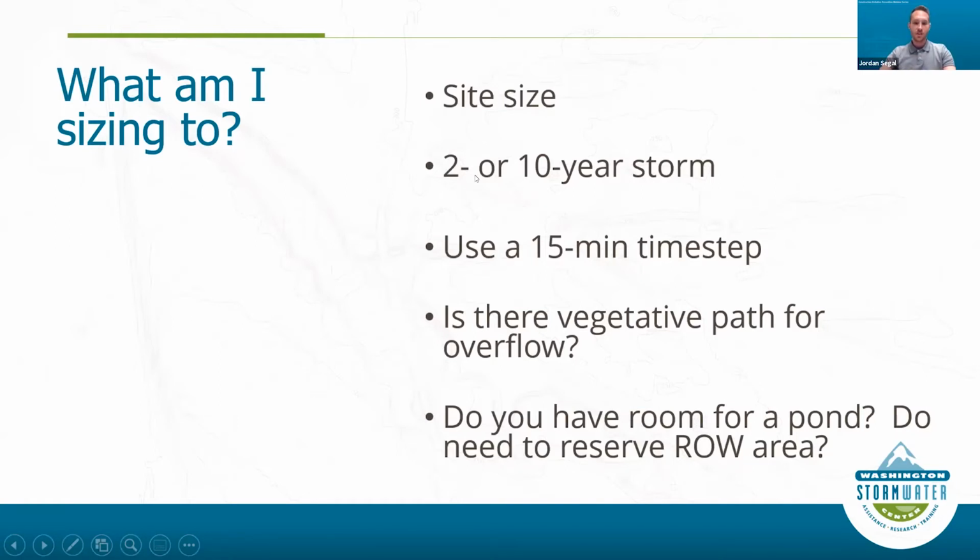But consider the 2-year or the 10-year storm, and using a 15-minute time step, you're essentially making a temporary detention tank. And then consider that overflow path. What if you just get more storm than you anticipated? And the idea is that, yeah, you might be designing in the summer, but there's always water out there.